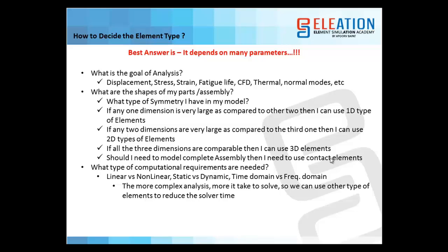Then also it depends on what type of computational requirements are needed. So do I have to solve this problem using linear or non-linear analysis, static or dynamic analysis, time domain or frequency domain analysis? Because if we have a complex analysis, then it will take more time to solve. So if it's taking more time to solve, then I can reduce the type of element to have a lesser number of nodes and elements, which might help us to get a solution faster. Otherwise it might require a higher hardware configuration to solve larger problems.